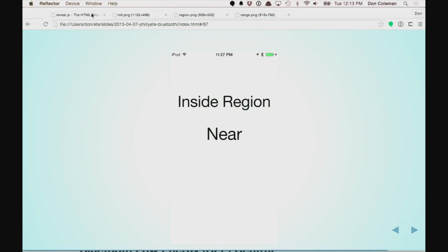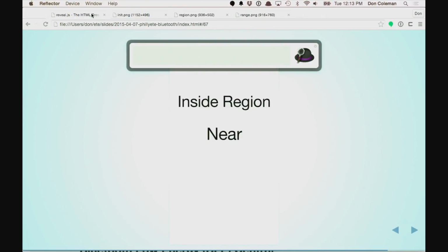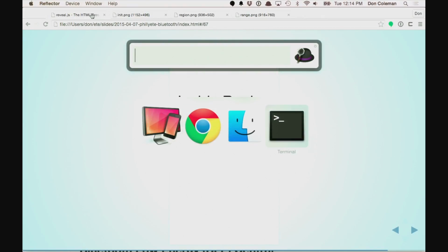So this is a little piece of hardware from Adafruit. It's called a Bluefruit LE Friend. It is an ARM processor that does a lot of Bluetooth stuff, and then it has a serial connection on the other side, so you can use it with an AT command set. So it's kind of neat for doing things like this. You can make it be a beacon, you can make it do some services, you can make it do a lot of different things. Typically with this, you'd use another beacon instead, but this lets me have less hardware while I'm doing this.